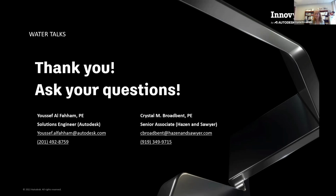Surge tanks are the one thing that provide energy to the system. However, again, it's up to the client to determine if they want to rely on other methods. I've seen surge anticipator valves work in some situations. I've seen air valves, enough of them, work in certain situations. You just have to get into the model and start playing around and find out what it is.